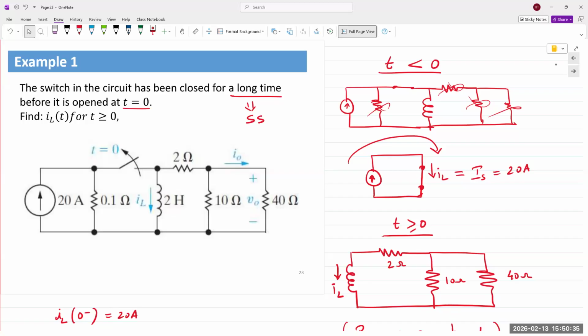That charging is very quick, and then it starts to discharge. And the discharge is very, very slow. So it charges up to maximum charge, and it starts discharging very, very slowly. Remember what I said, if it reaches, let's say, 10 volts, eventually, if you just leave it to discharge, it will discharge all the way to 0. But with the way these circuits are designed, that discharge is interrupted.